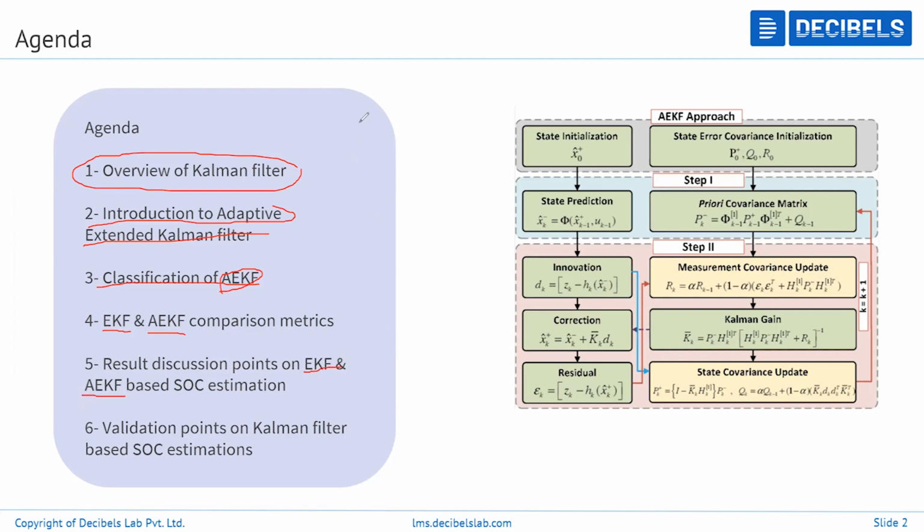With that we estimate the SOC of the cell or the battery pack, and I have results of both: the SOC estimation based on extended Kalman filter and the SOC estimation based on adaptive extended Kalman filter. We'll compare how they differ, and then we'll talk about validation points.